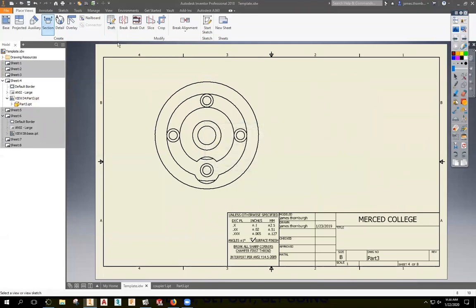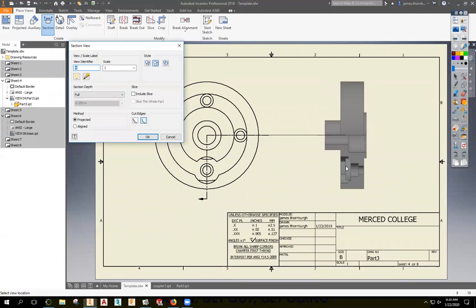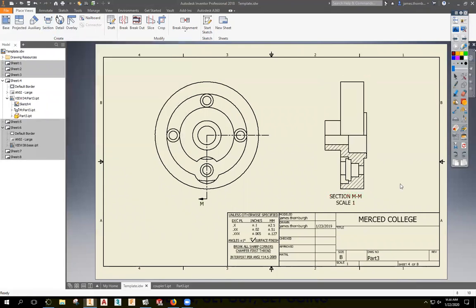Just, I'd see the bottom side. Okay. So when you do it, if you just move out here first, it's not going to give you any lines. You have to kind of move your mouse over something. And so now it's going to snap, it'll give you the projected thing for that thing you just moused over. Okay? So I click here, go in, pick the center point, go down, right click, continue. I get here. So now I get the bottom side as a section. Okay? Questions?